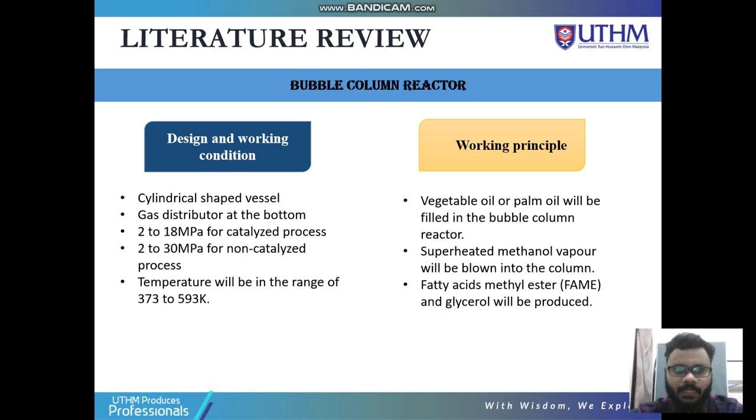Okay, for the bubble column reactor, I'm going to talk on the design and working condition. The bubble column reactor is normally a cylindrical shape vessel and has a gas distributor at the bottom. It normally works in a condition of 2 to 18 megapascal for catalyzed process, whereas 2 to 30 megapascal for non-catalyzed process. And this temperature will be in the range of 373 to 593 Kelvin.